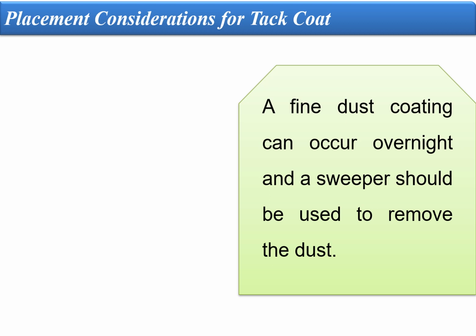So some of the placement considerations for tack coat: a surface free of substances is critical. A dirty or dusty surface will inhibit the ability of the tack coat to bond, potentially resulting in a slippage plane. A fine dust coating can occur overnight, and a sweeper should be used to remove the dust.